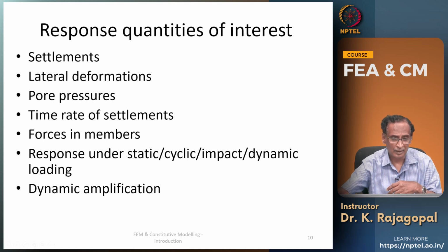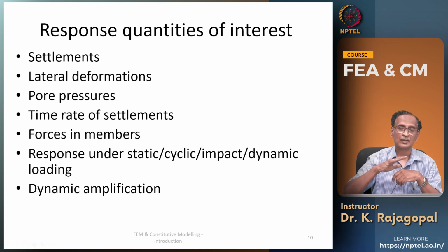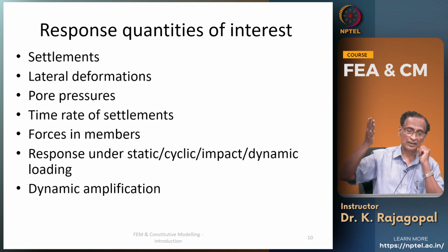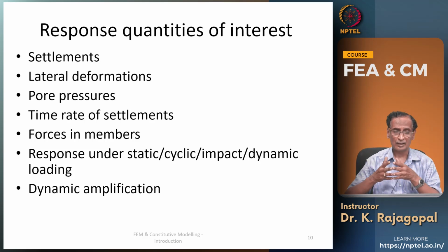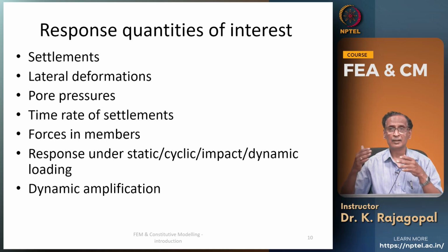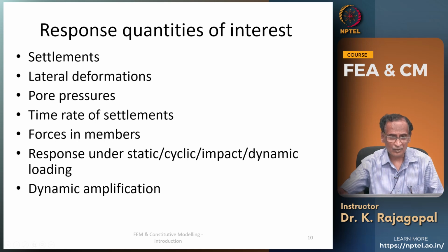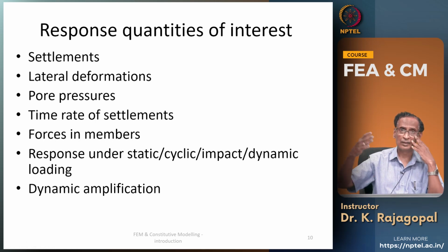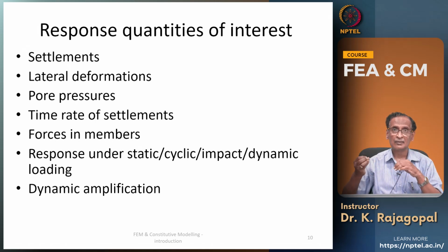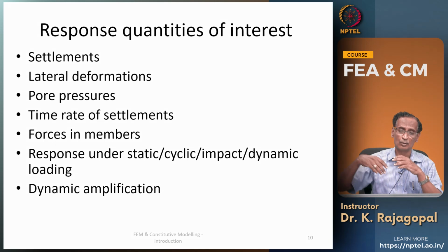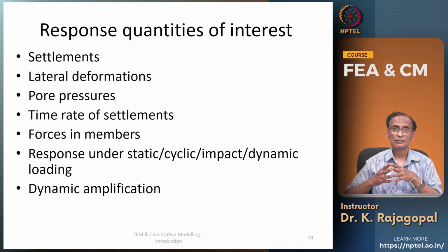Then what are the forces in the members, either a reinforcement layer or a sheet pile wall or your anchor? What are the forces that are developed that need to be accounted for in the design? Then we should be able to get the response under static loading or cyclic loading, where our load is repeated a number of times, and then impact loading, a suddenly applied load, or a dynamic loading, a harmonic loading or a seismic loading.